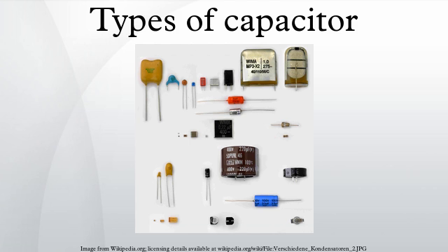Supercapacitors have the highest capacitance density because of their special charge storage principles. Electrolytic capacitors have lesser capacitance density than supercapacitors but the highest capacitance density of conventional capacitors because of their thin dielectric. Ceramic capacitors Class 2 have much higher capacitance values in a given case than Class 1 capacitors because of their much higher permittivity. Film capacitors with their different plastic film materials have a small spread in the dimensions for a given capacitance voltage value because the minimum dielectric film thickness differs between the different film materials. Capacitance and voltage range.